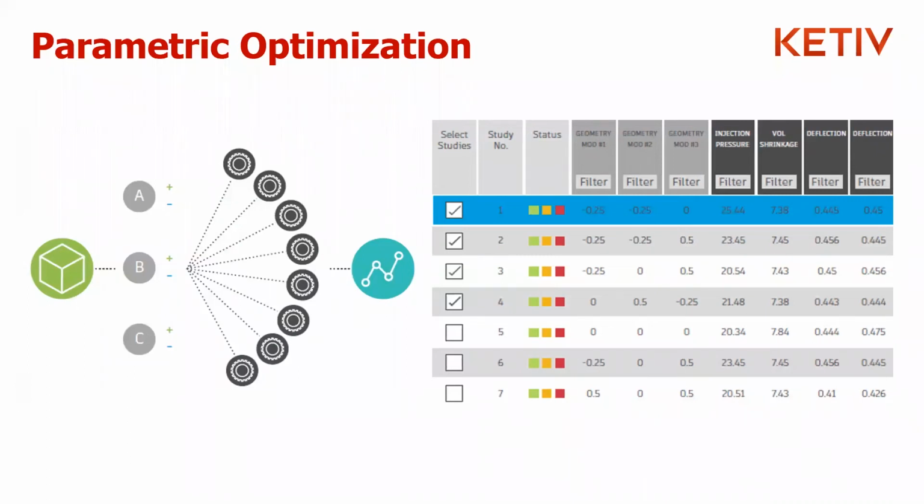Now, instead of manually adjusting each design variable as we did previously, with the example in the second slide, where the wheel hub that we had, we added gates to it, and then we saw that it added more weld lines, and so you tested that for strength, etc. Here in this case, you make your geometry changes, and instead of manually adjusting the design for every single variable, you can actually automate the analysis by defining a range of values, as we talked about.